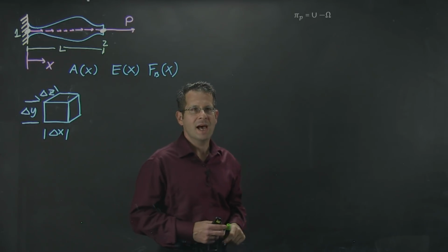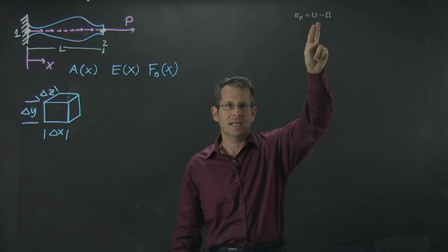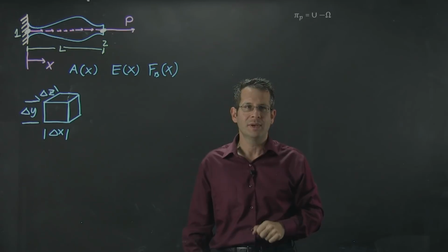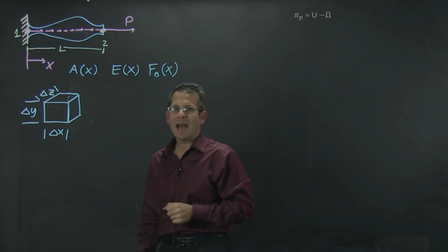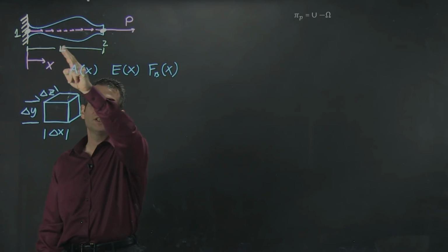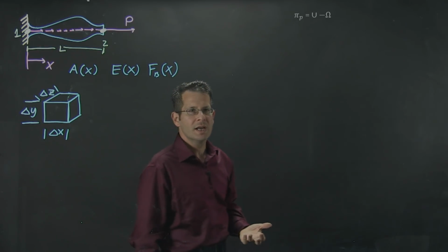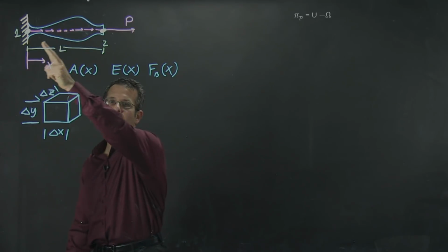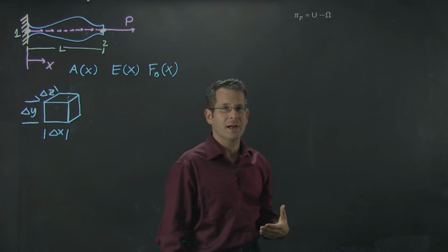Now, in the past, in order to derive the total strain energy inside of my bar elements, I've directly applied Hooke's law. Unfortunately, I can't do that on my more general case bar element because I can no longer assume that the stiffness is constant along the length of the bar. Hooke's law does not directly apply.